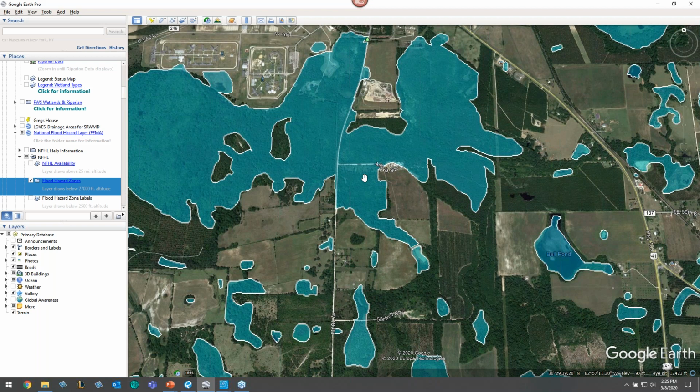Because if your project is above the floodplain elevation, you're not adding any additional dirt that wouldn't already be there in the first place. But if you're below the floodplain, then you need to compensate for that with a pond that digs out the dirt. That way, when this area floods, the volume of dirt that you're adding to the area can be compensated with the pond. And it's not really a pond because it's going to be dry almost the whole time until a 100-year flood happens. Then the water will just fill up into the pond and it won't overflow anywhere else.